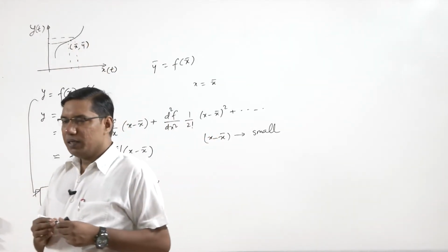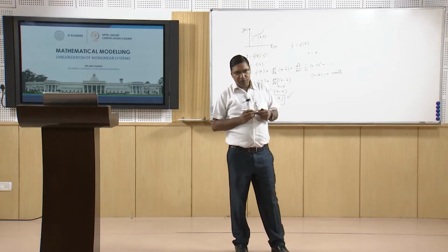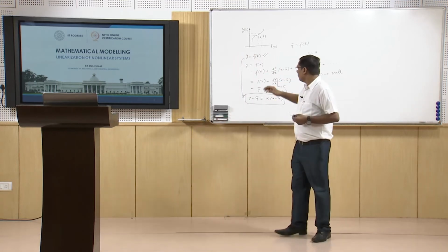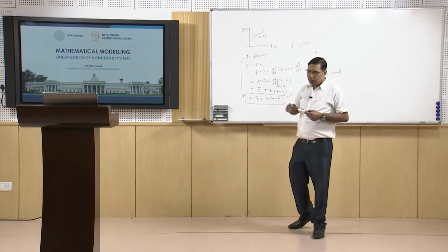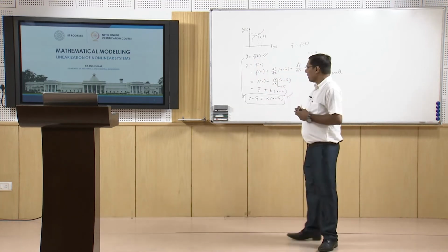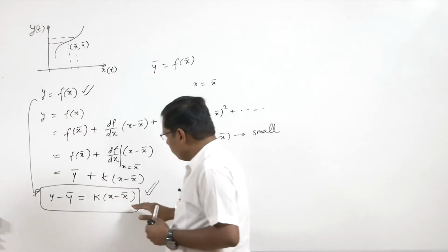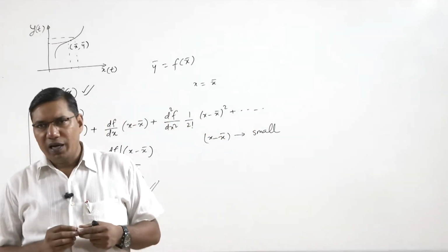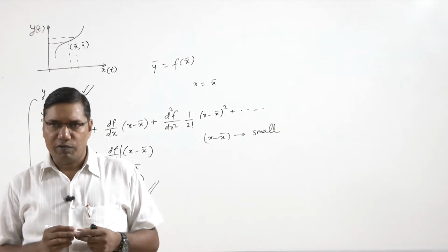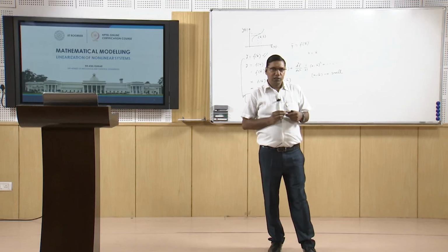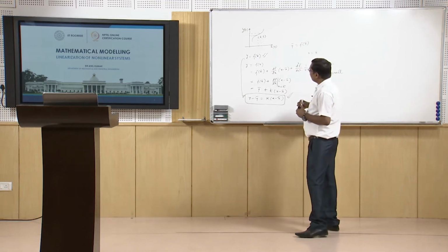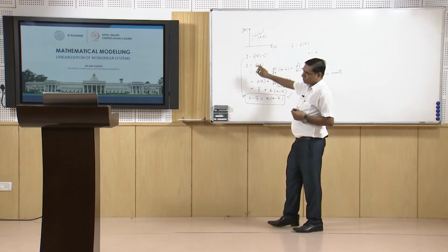So, now if any differential equation is formed that contains some nonlinear function f(x), we can approximate this to a linear function, and then we can apply the Laplace transform and find the transfer function for this nonlinear system.